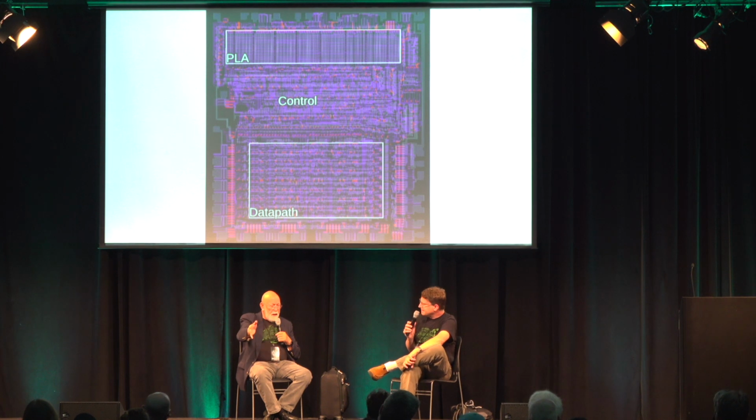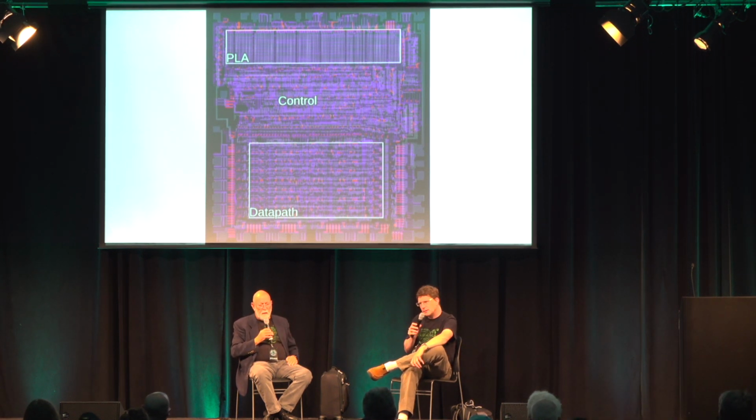Right. So we had true and complement. Right. Sure. And then on the timing states, we had the same. So that'd be 6 lines coming this way, 16 lines coming that way. We might have had a couple extra interesting lines. Sure, there's a few extra things, yeah. But that control, we called that the random logic, which would take what I call the min terms at the top, and that would do the random logic.